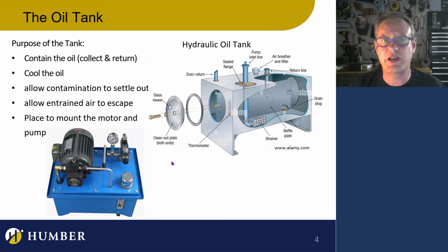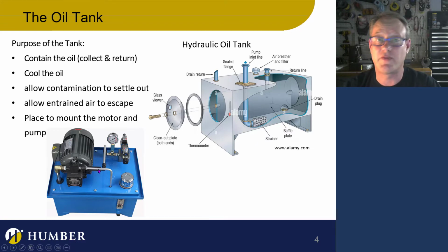It's also a really good place to allow the sediment, all of the particulates that are in the oil, to be filtered out and stopped from getting sucked back up into the system. We allow air to vent out. Air can get into the fluid itself, and there are some components in the tank that can really help to remove the air out of the fluid. And it's also a place to put the pump. In some cases, pretty commonly, you'll see the motor, the prime mover, and the pump itself sitting right on top of the tank.